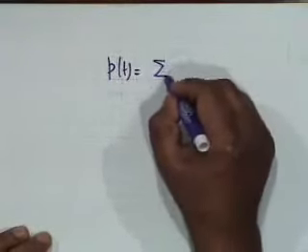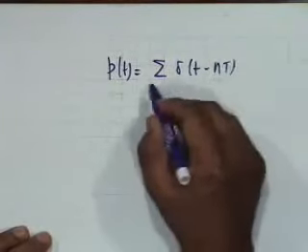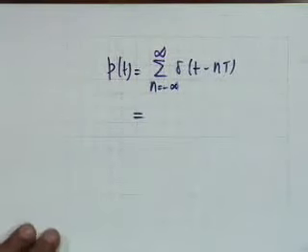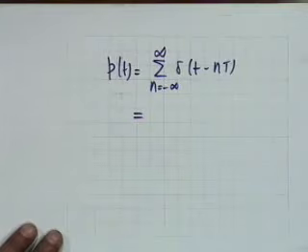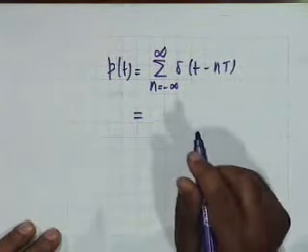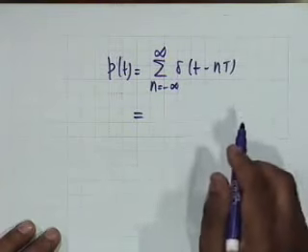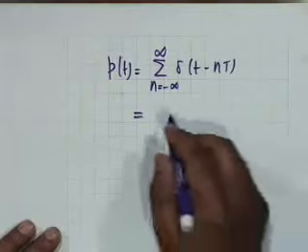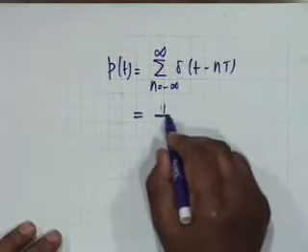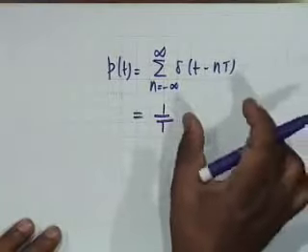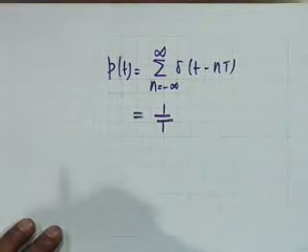All right. We had argued that p of t, which is a sequence of impulse functions delta of t minus nT, n equal to minus infinity to infinity, because it's a periodic function, we can expand it by Fourier series. This is where we did the example. And the Fourier series coefficients were all 1 by T, not 2 pi by T. It was simply 1 by T, because within one period there is only one impulse.